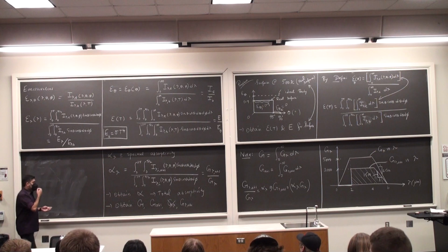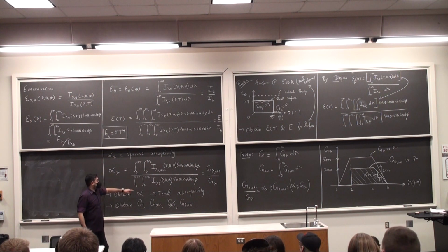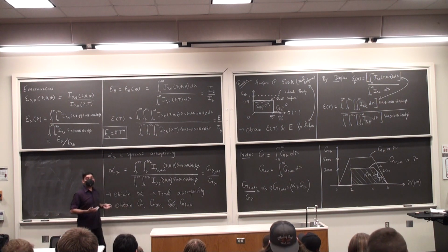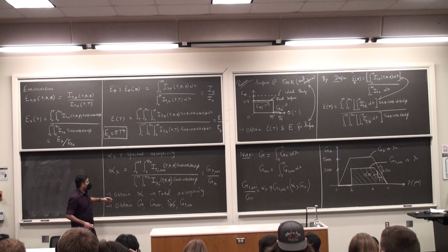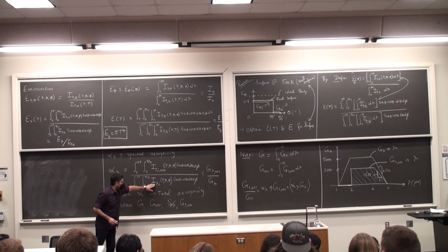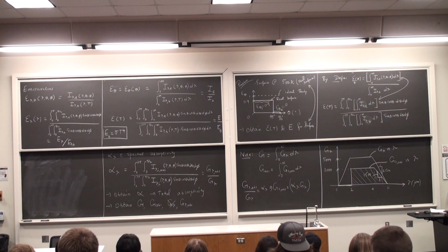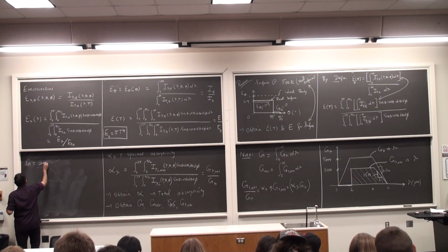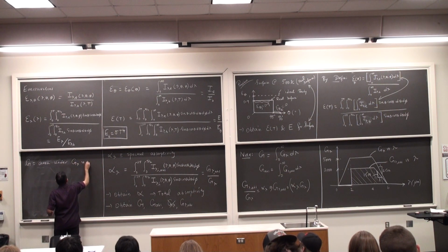The big issue is, okay, how do you get these values? This is obtained from experiments. The bigger issue is, okay, in terms of irradiation, I don't know these creatures. We're going to make some approximations in the next lecture and say that under certain circumstances, if the surroundings are diffuse, I can equate this to the radiation coming from an ideal surface. And when are those valid? Okay, those are things that we're going to see. Okay, so G is the area under the G lambda versus lambda curve.